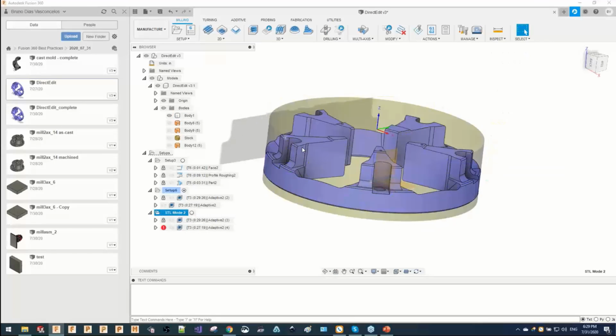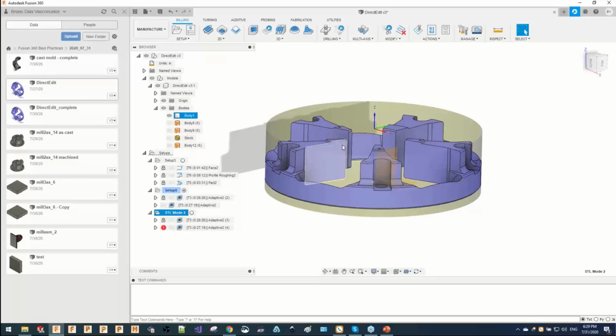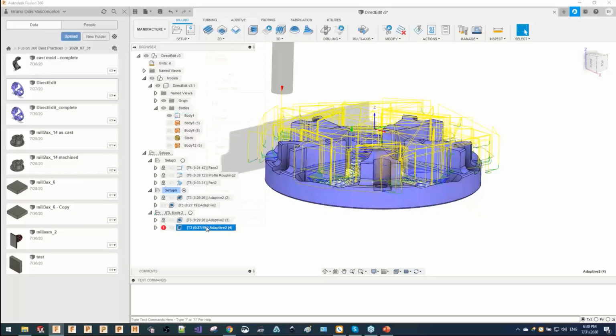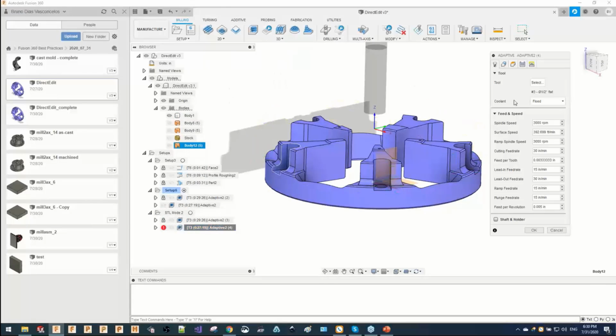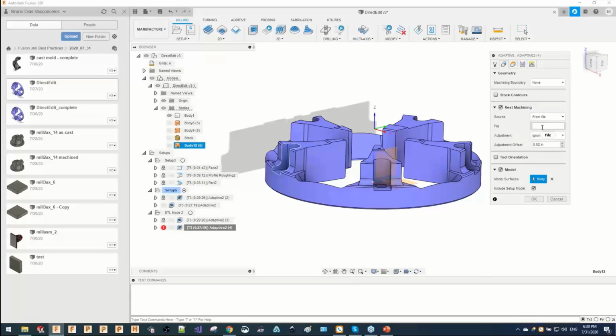In case your stock material from the setup is not from an STL file and is not representing the correct stock material, you can always come here and choose rest machining from STL, from file. The software is waiting for an STL selection. In HSMWorks and Inventor HSM, I believe you have a browse button here to browse the file in Windows Explorer. In Fusion 360, there is no such button.